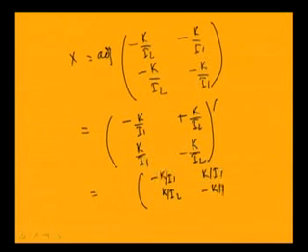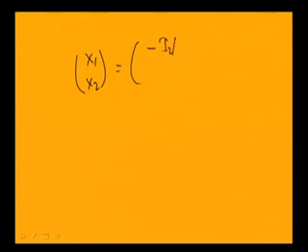So, in this case also you just observe that both columns, if you normalize, will be the same. So, you take any of the columns and you normalize it. So, in this case you will get x1 x2 equal to minus I2 by I1 and 1. So, in this case you just observe that this amplitude ratio is the inverse of the inertia ratio. So, if you know the inertia of the system, in that case you can find the amplitude of the system by using this relation.